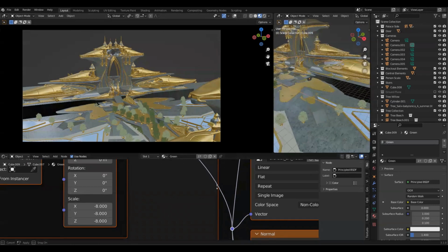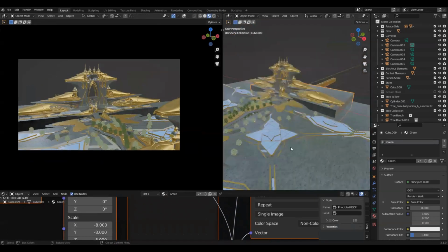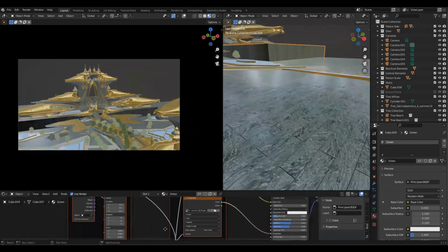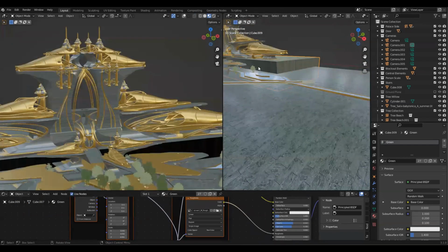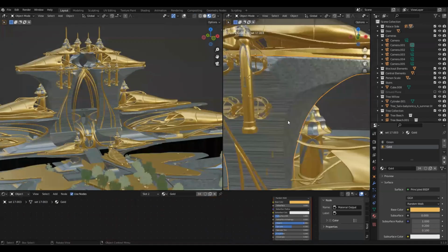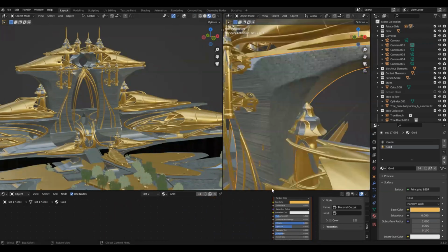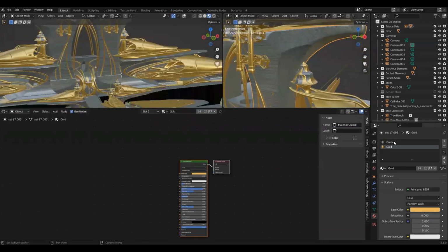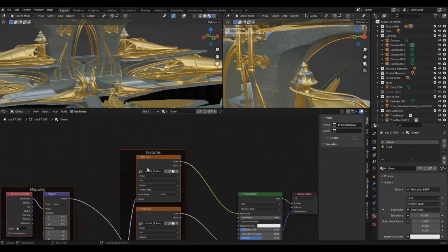Okay, so you'll notice a few things we need to do. In the assets that were just simple boxes, this method of unwrapping the maps is working. But on these assets that we imported from 3D Coat, it's getting all stretched and it's incorrect. So what we actually need to do is click on the green material again to view the nodes.